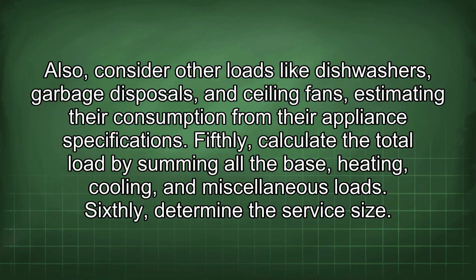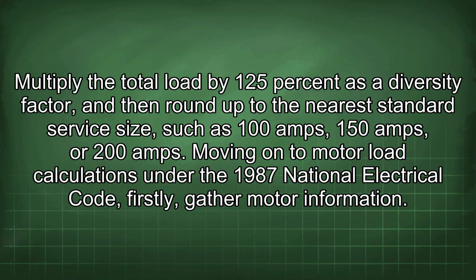Fifthly, calculate the total load by summing all the base, heating, cooling, and miscellaneous loads. Sixthly, determine the service size. Multiply the total load by 125% as a diversity factor, and then round up to the nearest standard service size, such as 100 amps, 150 amps, or 200 amps.